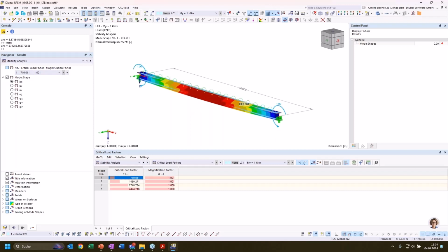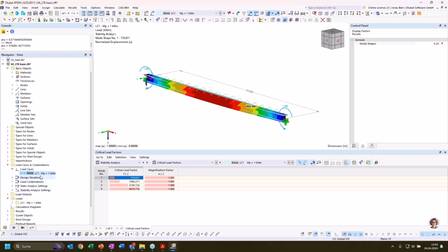because you may want to perform a lateral torsional check, like using a second order theory analysis with imperfections, and maybe you want to also have these rotational restraints be effective in the global analysis. So that's why we added this option through the structure modification.